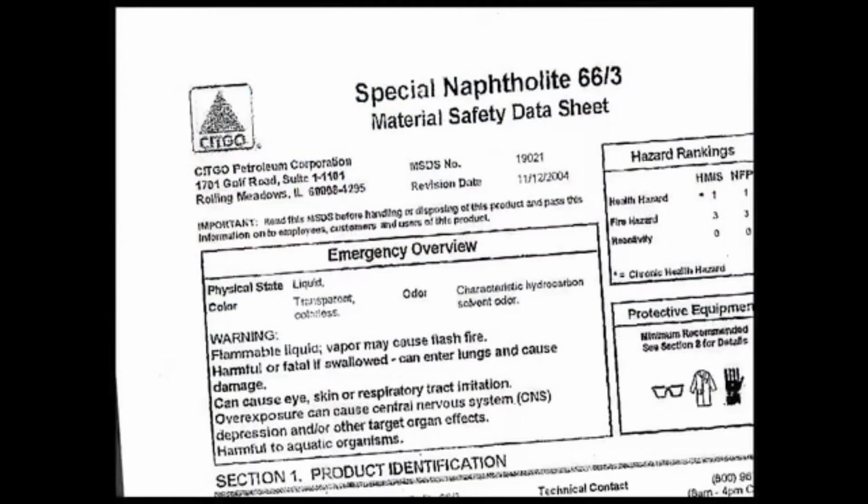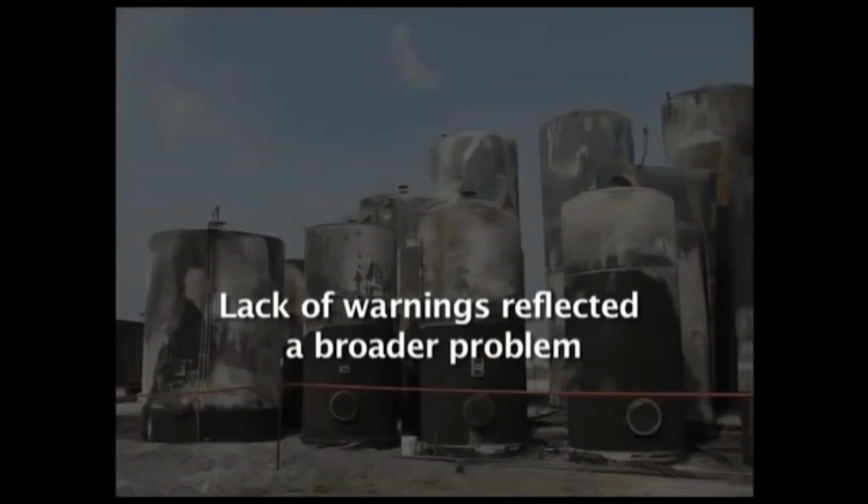The MSDS for the naphtha supplied to Barton indicated the solvent could accumulate a static charge, which could spark and ignite vapor. But the MSDS did not warn that the naphtha could form a highly flammable vapor-air mixture inside a storage tank. And apart from normal bonding and grounding, the MSDS did not include any special precautions against static ignition.